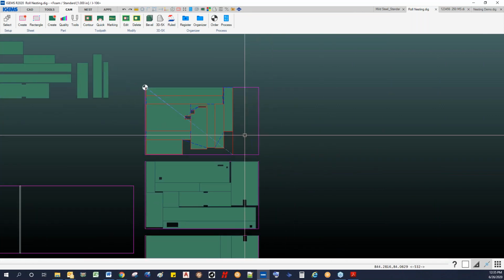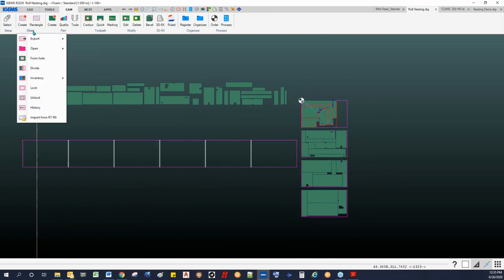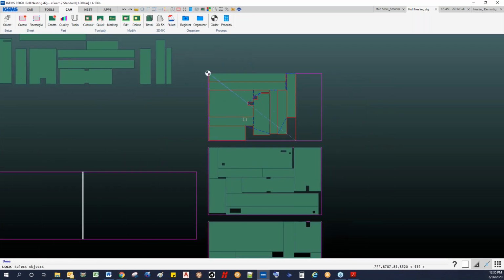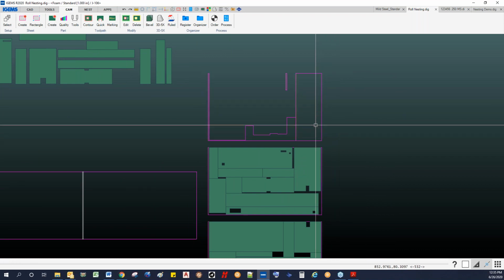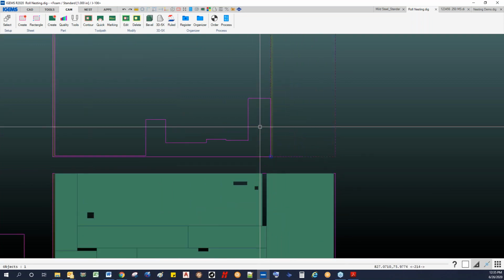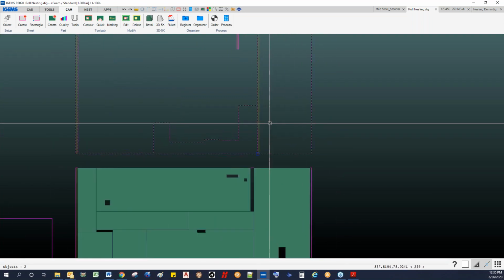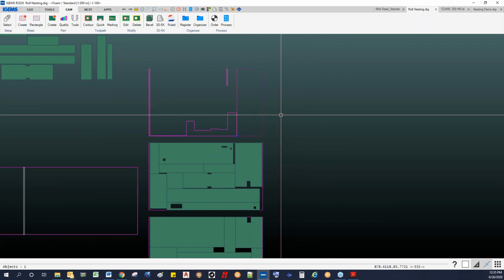And then finally, once you're done processing your sheet, you want to put something back into inventory. There is the option under the sheet area here to lock your sheet. So if I click on this lock button here, that's how I got that original remnant sheet that I showed early on. You can select your sheet and it'll go through and recognize a couple different sheets here, and it breaks this up. So obviously this here you want to keep, but it breaks this up, and then you can take this and you can inventory that.